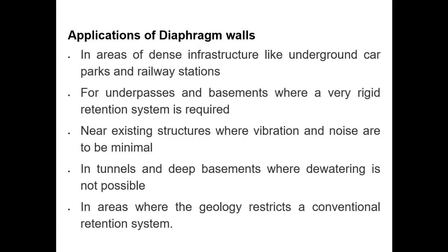The applications of diaphragm walls are: they can be used in areas of dense infrastructure like underground car parks and railway stations, for underpasses and basements where a very rapid retention system is required, near existing structures where vibration and noise are to be minimal, in tunnels and deep basements where dewatering is not possible, and in areas where the geology restricts a conventional retention system.